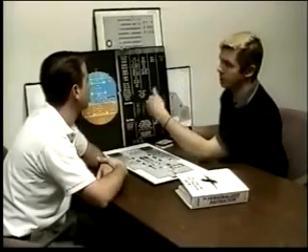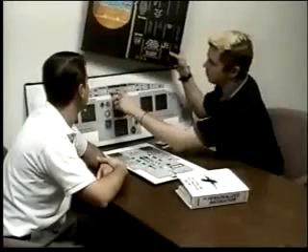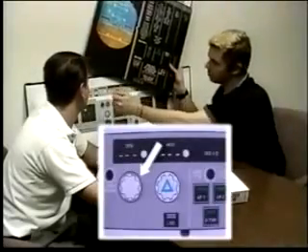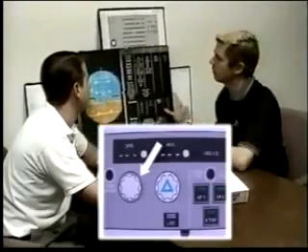What this does is, it means I want to climb at a specific preset speed or descend at a specific preset speed. And that's going to appear as a managed speed in the speed window. During expedited climb, it's going to climb at green dot. The problem with green dot is that it's really slow. Yeah, it's L over D, but we don't want to be getting down to 210, 220 knots. So an easier way is to do an open climb at about 250, 240. You can figure it out, you're a big guy. The expedited descent then references 0.80 or 340 knots. If you happen to, for whatever reason, while you're in an expedited mode, pull the speed knob and select something else, you're going to revert to either open climb or open descent, whichever is appropriate.